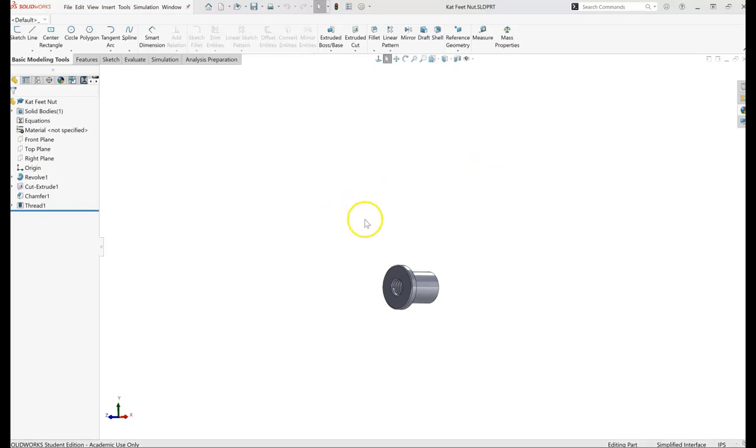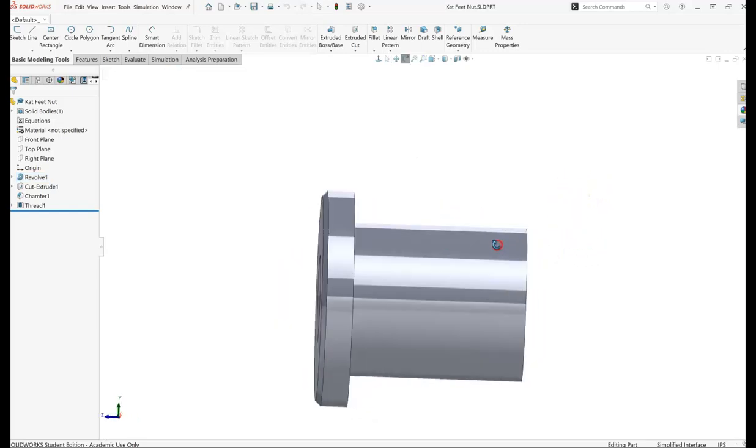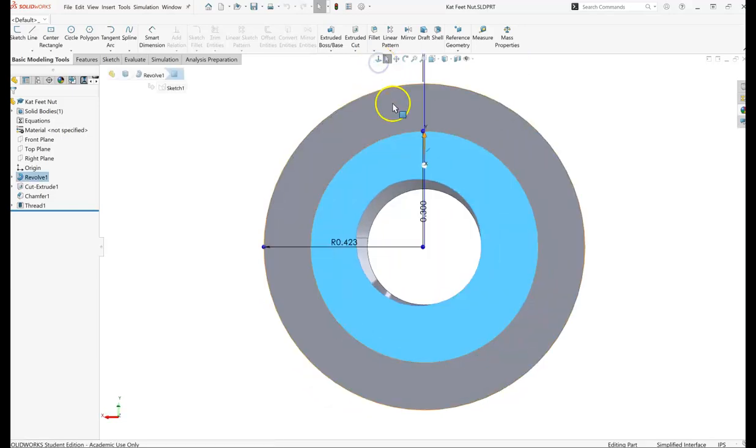If I click on a surface and then click normal to, it's going to rotate it, and so what normal means is now I'm facing that surface. A little hard to show you all the surfaces and how that works on a cylindrical project, but I could do the other end as well. Click normal to, and it's going to turn, it's going to face. So you can imagine a part with multiple sides, and I might want to get a view of looking straight on that part.